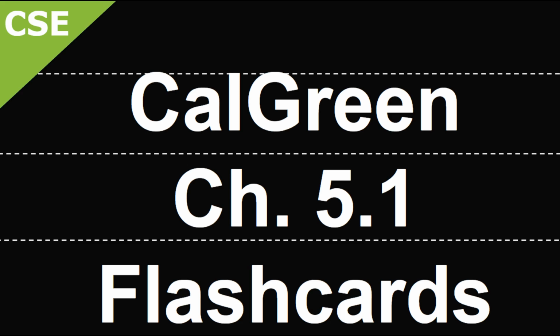Electric vehicle requirements are generally for new construction, new buildings on new or existing sites with new or pre-existing parking stalls. We'll discuss some updates to existing projects with additions and alterations in a few minutes, which have new requirements as of July 2024. For this section, let's focus on new construction and new buildings. EV charging must comply with CalGreen and provided in accordance with regulations in the California Building Code and the California Electric Code.